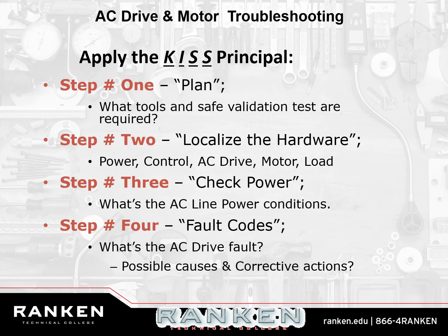Sometimes it can be as simple as the thing's just flashing at you, and it's telling you what the fault codes are. But sometimes if people have eliminated the fault codes, you have to go back into the fault history and pull them back out of the memory of the drive. So it's not as easy as it sounds, but if you can pull the codes out, you can figure out what's wrong with it normally.